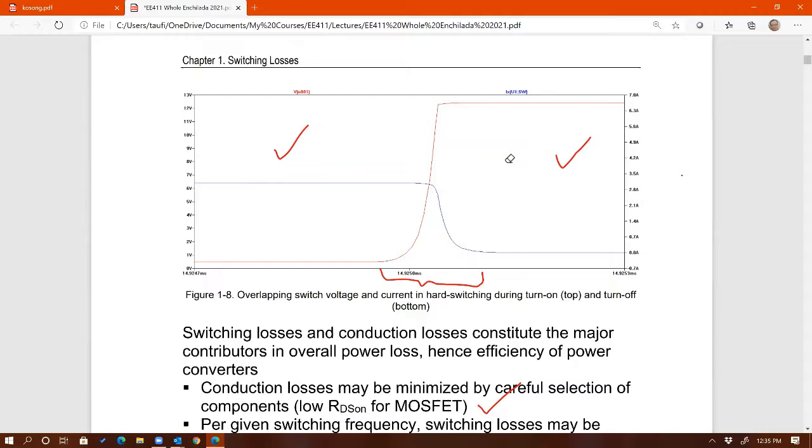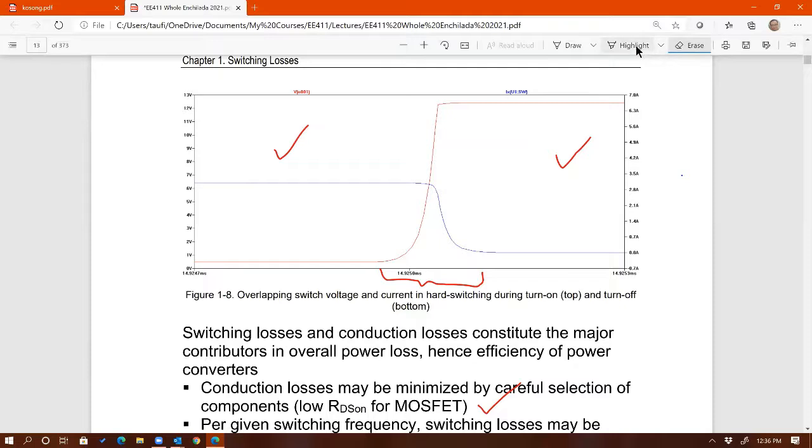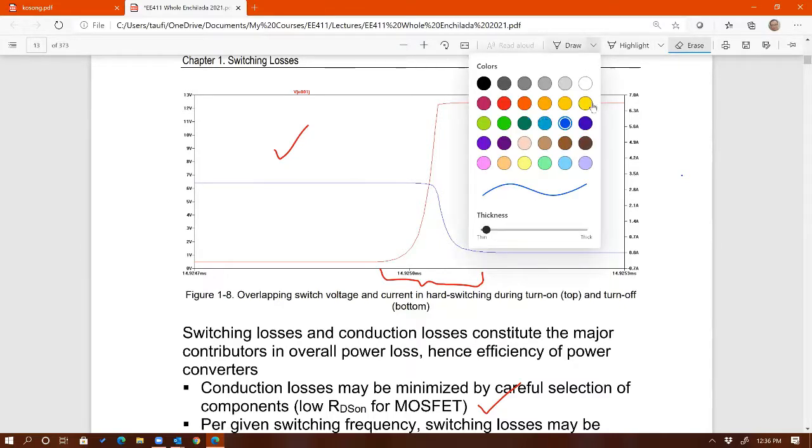Oh, I got you. That's the soft switching for later. That is actually the concept behind soft switching: once you turn the MOSFET on and off, you introduce external components to reshape the voltage and current waveforms of the MOSFET so that they don't follow a square wave. Okay, so that's the concept behind soft switching. Hopefully that answered your question. No, that makes sense. Okay, good.